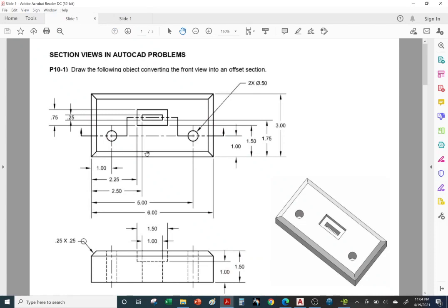We have a second rectangle on the inside, and the reason for it is because we have a chamfer going along the edges. A chamfer is a straight cut at an angle. It's not round, it's flat, but it's at an angle, typically 45, 30 or 60 degrees, but 45 degrees is the most common. As you can see, the callout for the chamfer is 0.25 by 0.25 inches, and the circle on the leader indicates that it goes all the way around.